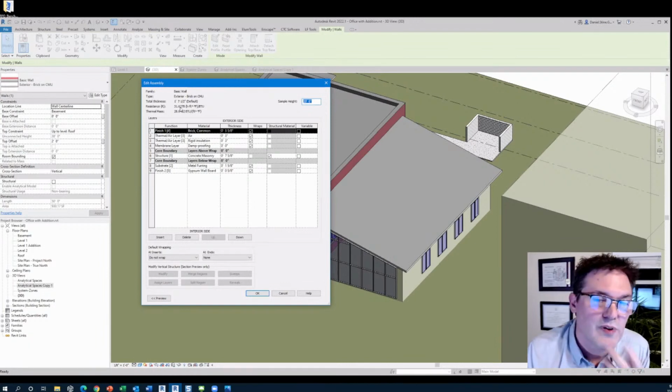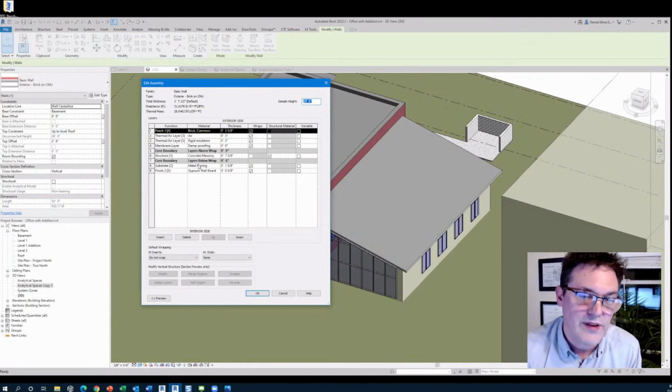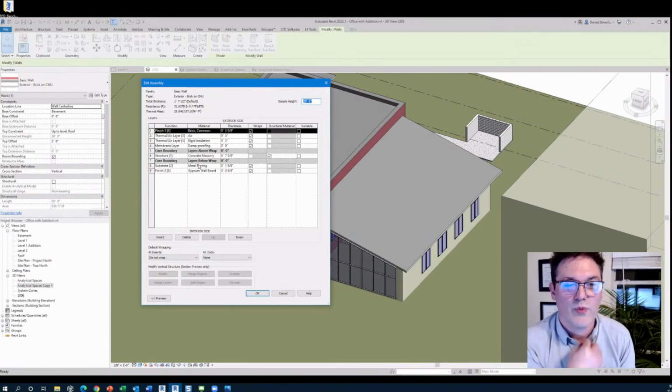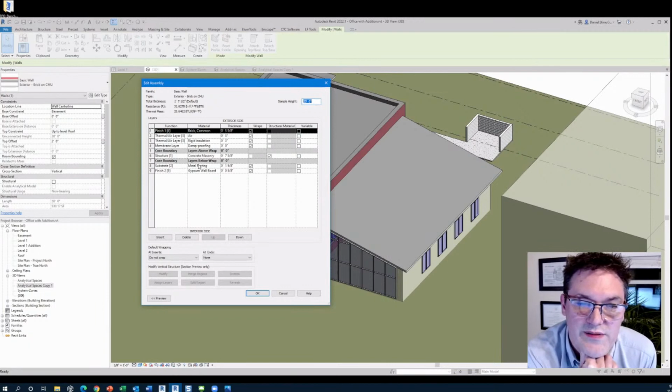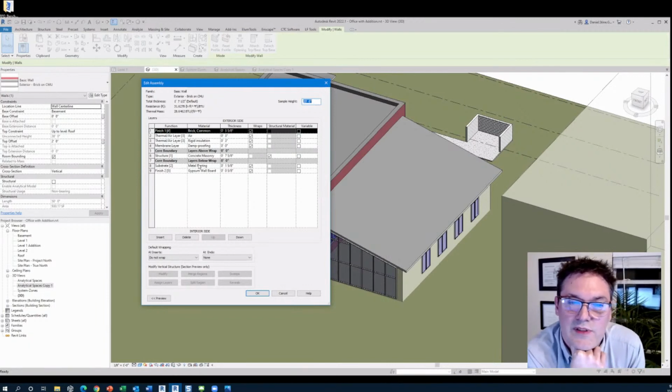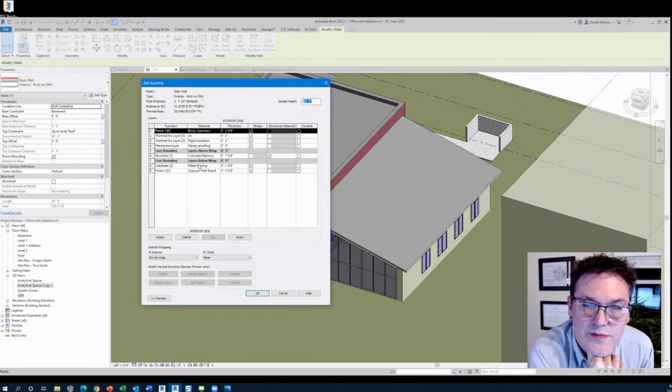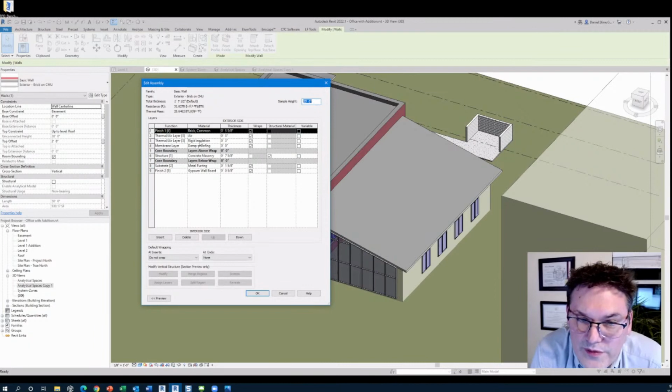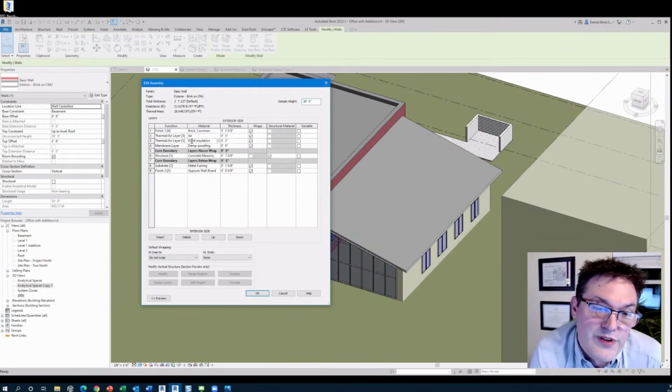And I've written blog posts on how you can actually tweak the materials to account for the weighted approach of studs versus insulation, and do the derated method, right? But for each one of these layers, you would have to derate them when you're setting up the materials, right? Yep. It won't derate the material during the energy model. We'd have to. And this is a pretty cool workflow.